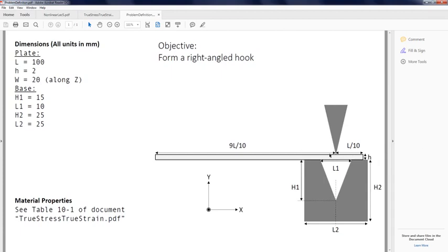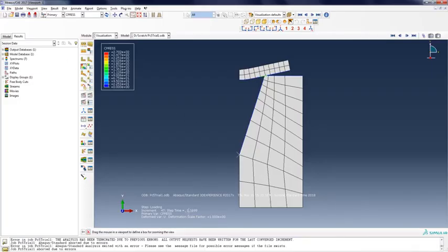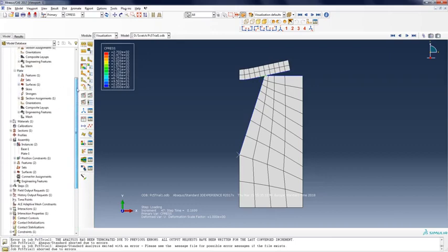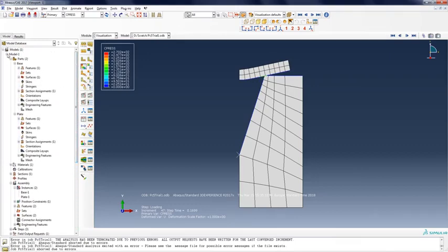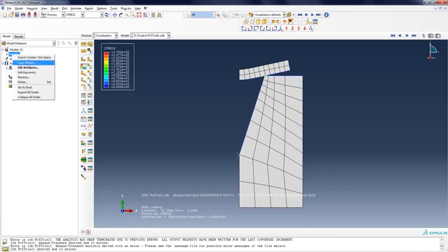And let's see if we model the problem as an experimentalist and try to include these curved loading tips and fillets, and see if they can improve on our convergence. Now we are here at 0.17 step time. Let's modify the model. Let's copy the model to model 2.